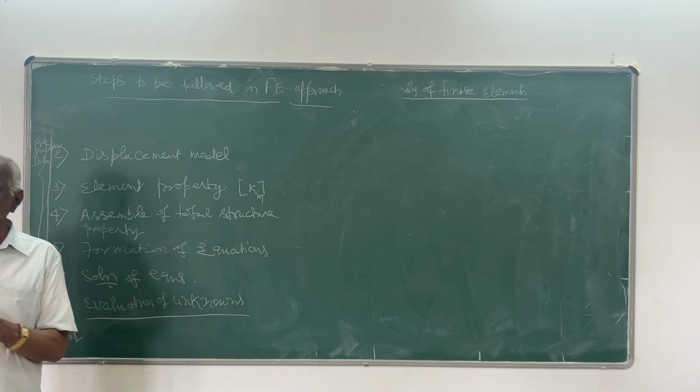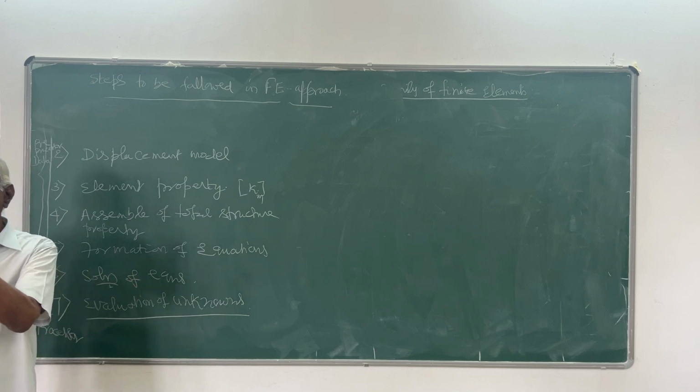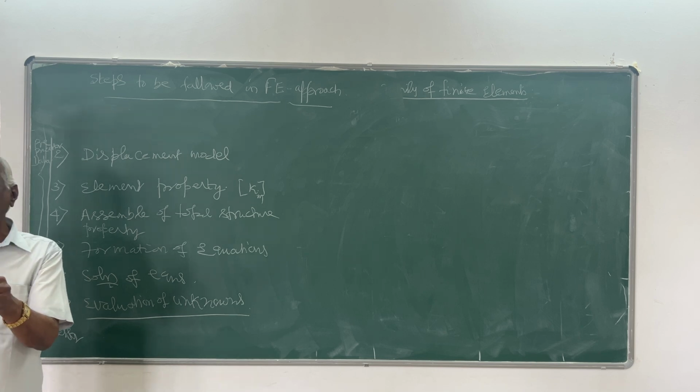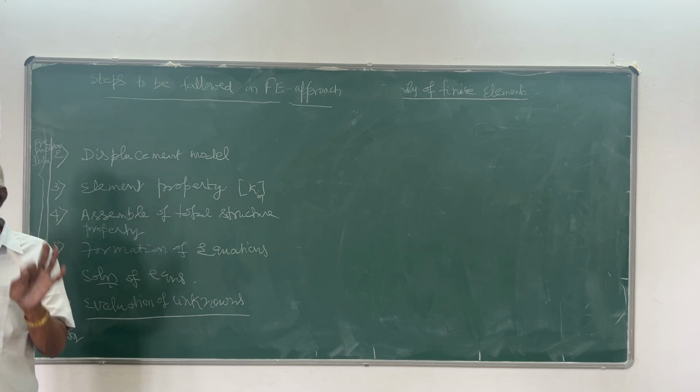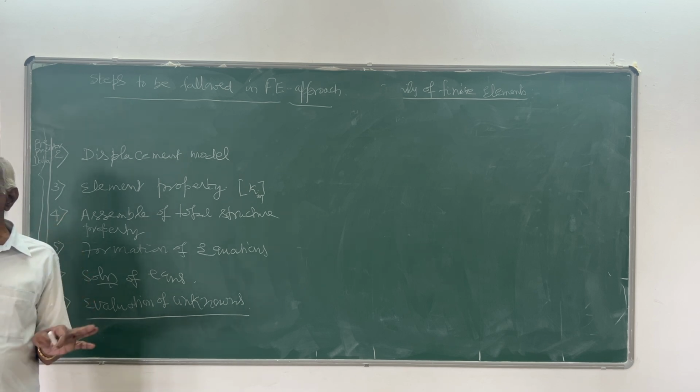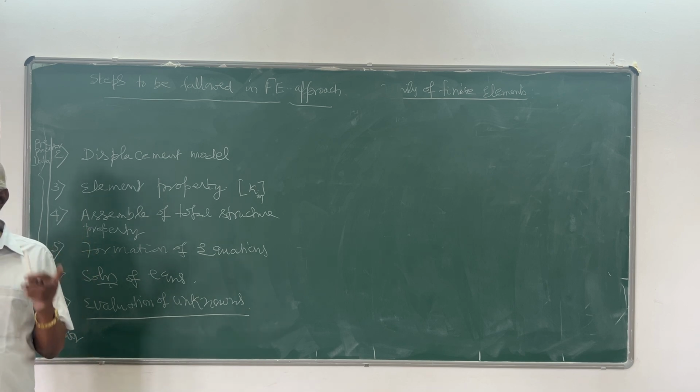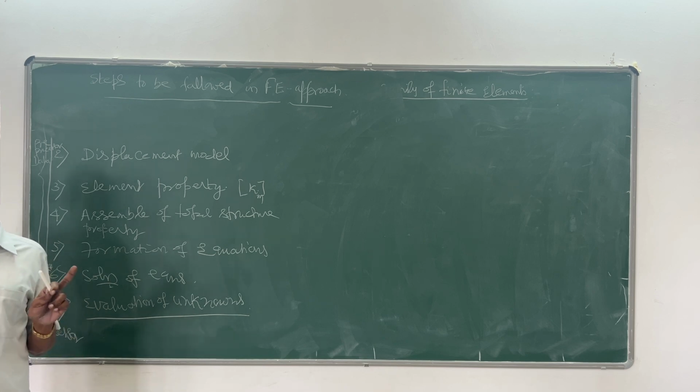No other way. Even if the element is inclined, there is no resolution of components involved. It is only one direction, that is along the axis, the local axis. The force or displacement in bar problems or spring type problems will be only axial.